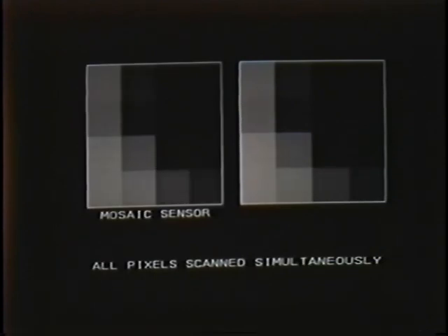The type of sensor that produces images like these is known as a mosaic sensor. It is called this because the sensor actually consists of many detectors held together in a focal plane array. Each pixel in an image is the product of one of these detectors. The key element of a mosaic sensor is that each of the detectors, in a sense, takes a picture simultaneously. In other words, the 16 pixels in our blinking image here are all produced at the same time, as if they were 16 individual pictures. Each of these pictures is then put together, like a mosaic, to make up the image.